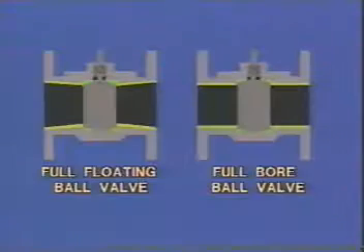There are a number of other variations of the full ball valve. For example, a full bore ball valve can be used where service conditions require that lines be pigged or rodded out. Three-way ball valves have a flow passage that makes a turn within the ball. These can be used on converging and diverging streams. Four-way valves also exist. Segmented or characterized ball valves utilize a segment of a ball which is supported by stub shafts. The leading edge of the ball and the inlet port are specially shaped to achieve a different flow characteristic.